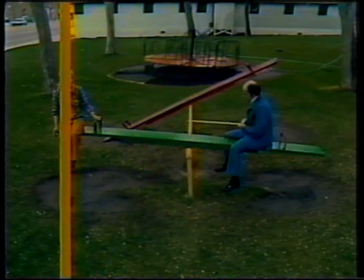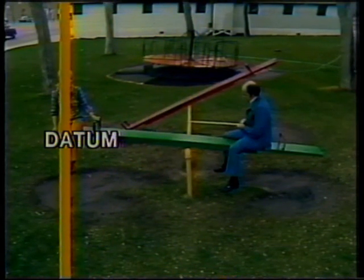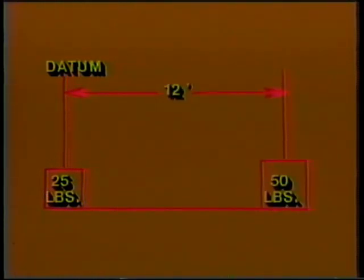We could just as well have located the datum at the center of one of the weights. Here we have a 25-pound weight on the datum and another weight of 50 pounds 12 feet to the right of the datum. Since the 25-pound weight is on the datum, the arm is 0 and the moment is also 0. The 50-pound weight is acting on a 12-foot arm to the right of the datum, a positive 12-foot arm.